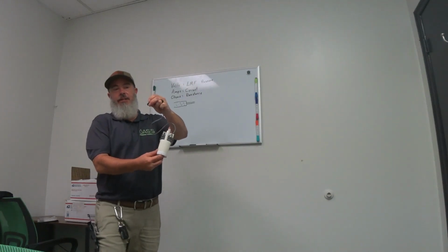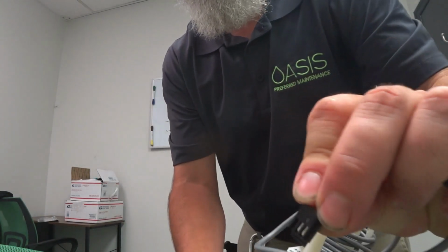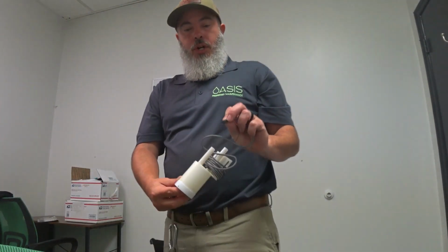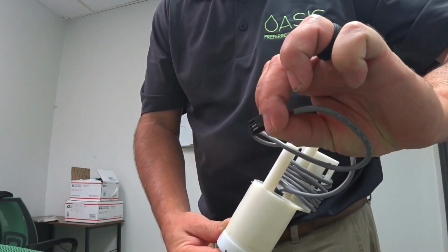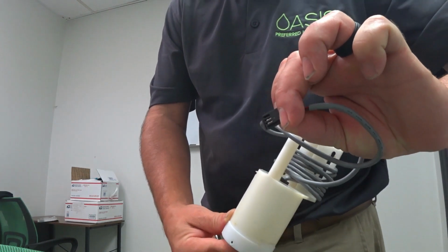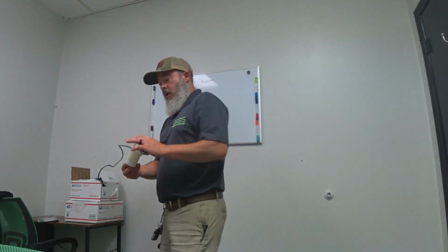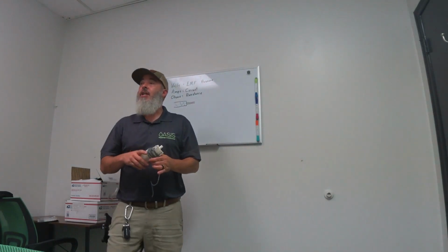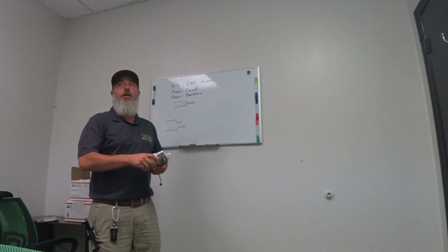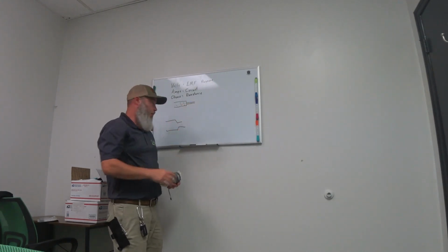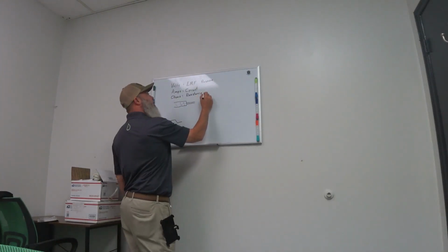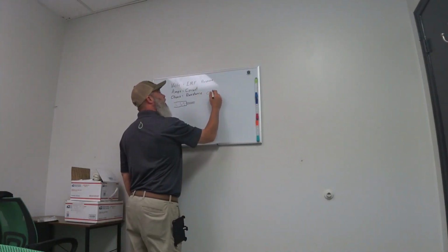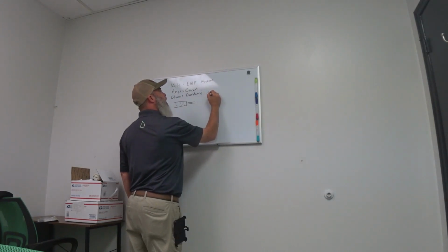And then it's got, if you can see, right here, those 2 metal tabs right there. You just put one lead on one of those metal pads, and then you put the other lead on the other metal pad with your multimeter in ohms, because we want to test the resistance. And what we want to have is continuity.